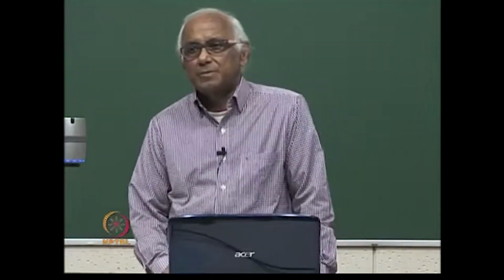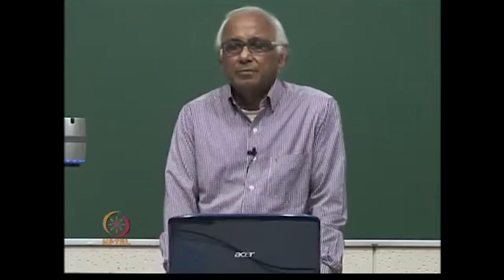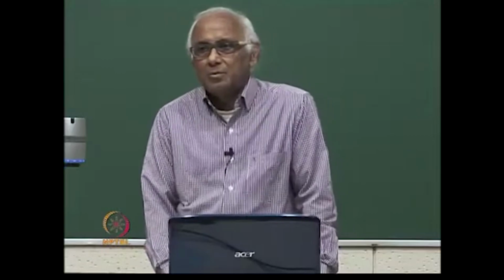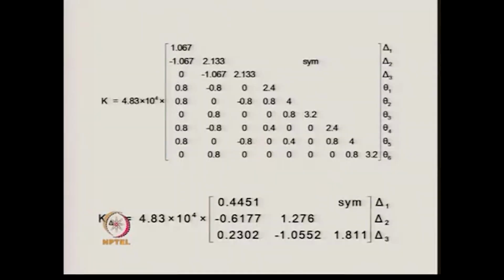Therefore, for the subsequent time interval and subsequent increment of loading, we will replace that plastic hinge by an ordinary hinge, which cannot take any moment. Therefore, it becomes 0. Similarly, corresponding to theta 6, we also put 0. In that same fashion, the second column, third column, fourth column have all been generated.